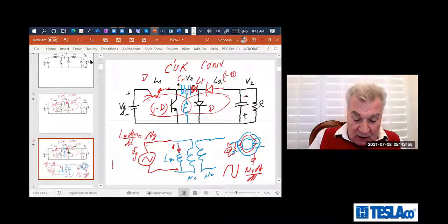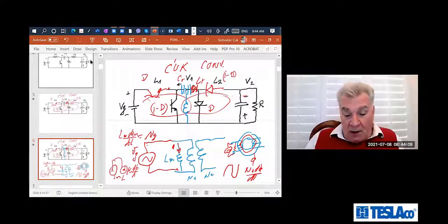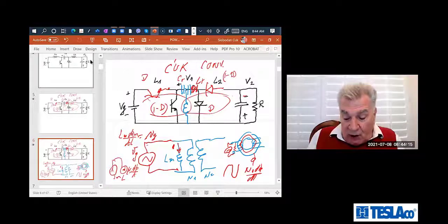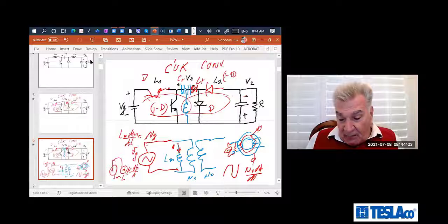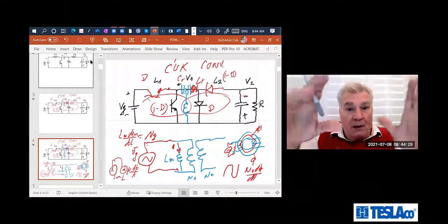You see what I'm saying? So you have the driving voltage, and then you have this voltage, N1 d phi per dt. So there is a whole circuit balance. Input voltage generates a flux in the core, and that unique flux in the core makes everything possible. By Faraday's law, this flux generates a voltage which is opposing the driving voltage and makes it, in a loop, equal.